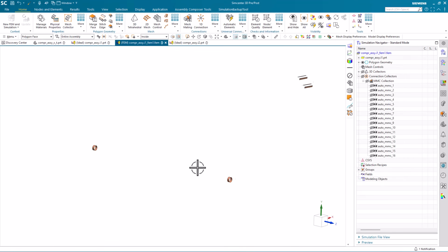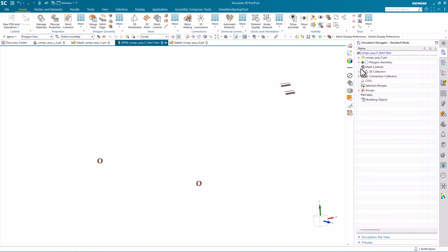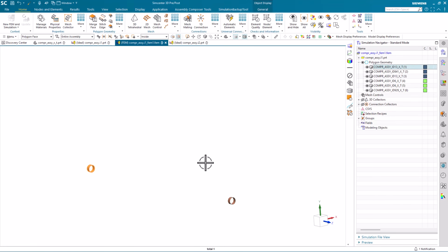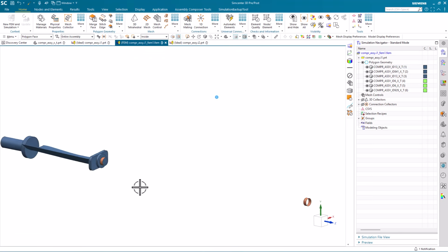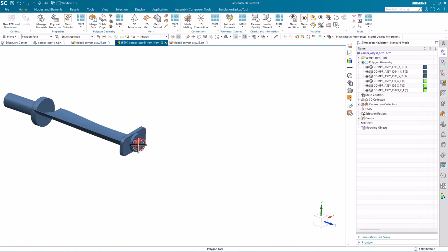And then if I just mouse over a given face, it should be one face selected there. So one object is selected there, one object is selected there, and then you can just start to display maybe these bodies. I'll start turning on these bodies that are shared. So I can see that only one of these two faces is selected. So this one body is going to be the stator vane. So I go ahead and select that. You can see that it's connected to this mesh mating condition face as expected.